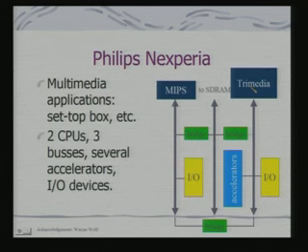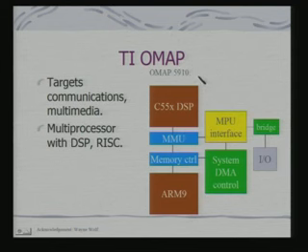Since Trimedia was primarily designed for media processing like video and image processing tasks, this SoC, that is, application platform, was designed by Philips particularly for applications like set-top boxes. TI OMAP has the C55X DSP, which we have studied already, as well as ARM9, these two, and there are variants. We are looking at one particular OMAP, and they are used together for multimedia as well as, in fact, handheld portable communication terminal applications.